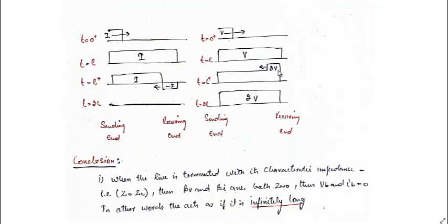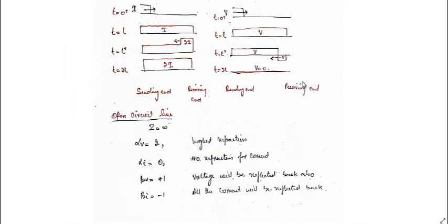So voltage will build up in the open circuit. That's why the open circuit voltage for a long transmission line will be higher compared to the sending end. We can say that is the Ferranti effect. This also tells us the same. When it is reflected back, the total current will be equal to 0, because of the summation of the two. Here the voltage has reflected back with positive magnitude, and the total voltage will come out to be equal to 2. It means the voltage is building up to a higher value depending upon the voltage and the capacitance present in the circuit. So this is how the short circuit and open circuit can be demonstrated pictorially.